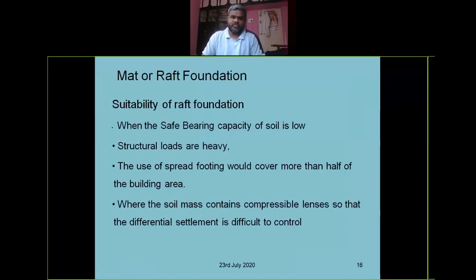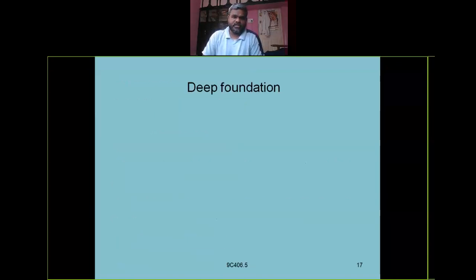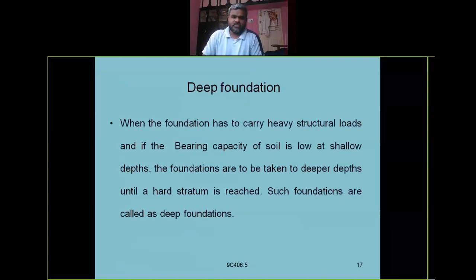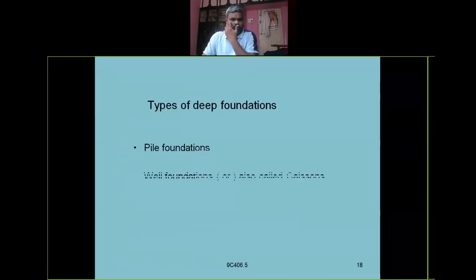Raft foundations are suitable when structural loads are heavy, when the bearing capacity of the soil is low, and when the use of spread footing would cover more than half of the building area. Then we'll go for mat footing. Then we enter into deep foundations.